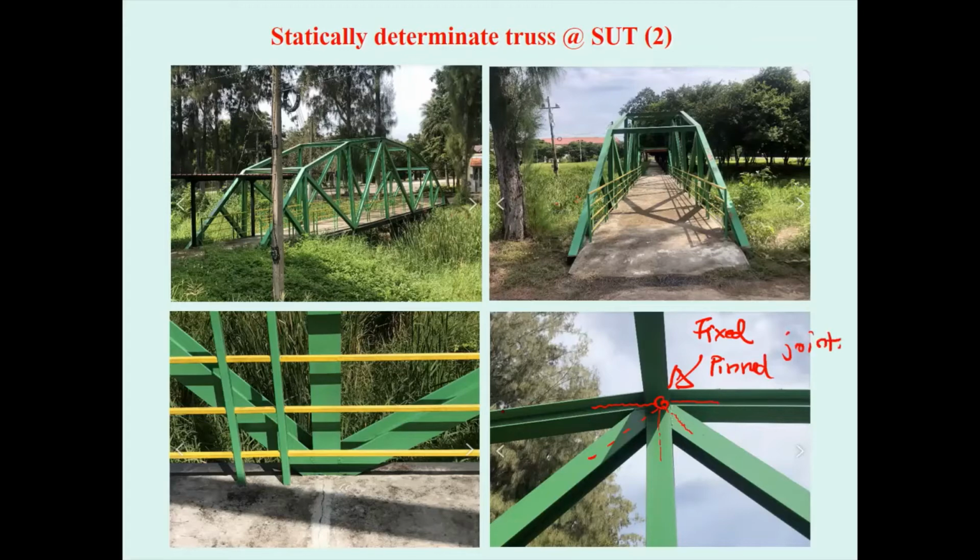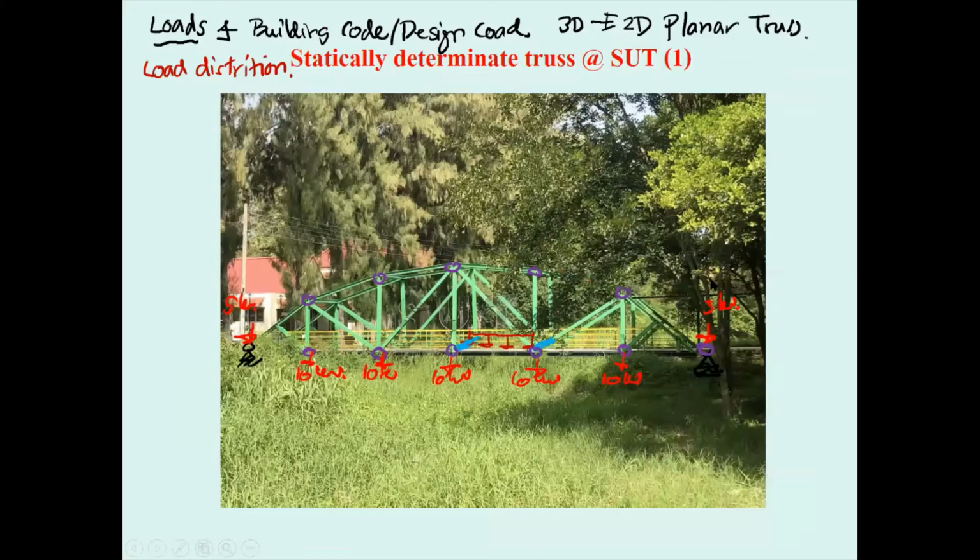When the force is applied only at the joints, okay, the members of the truss will be two-force members. Mainly, they take care of the axial force. Okay, the shear force is approximately 0. The bending moment that occurs in the fixed joint is approximately 0, or negligible, very small compared to the axial forces. Okay, that is for our understanding. And then what do you do next?